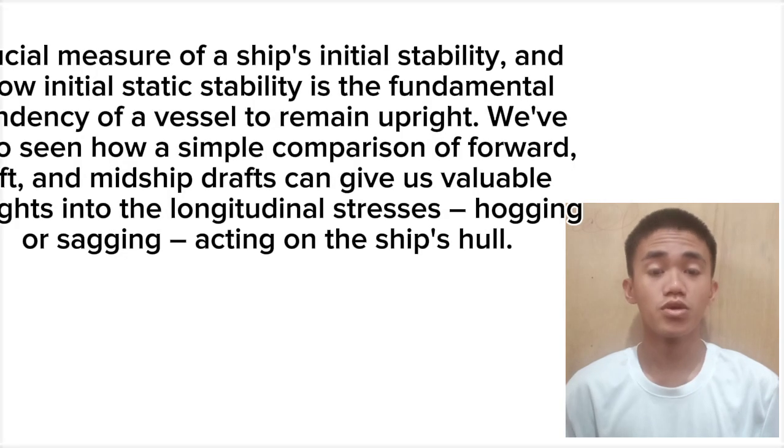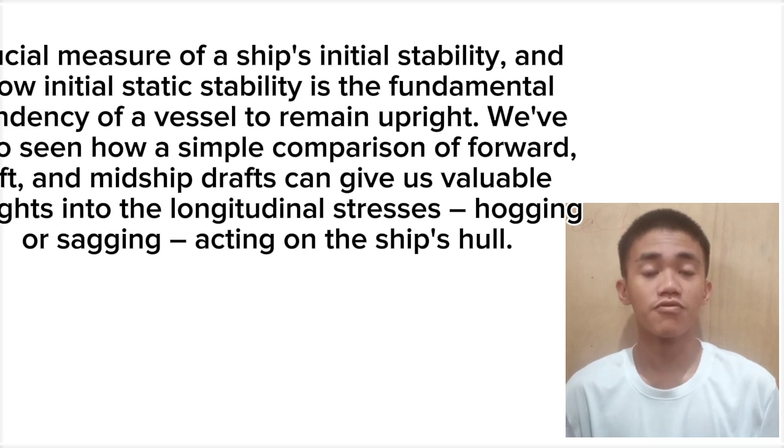In summary, we discussed how metacentric height provides a crucial measure of a ship's initial stability, and how initial static stability is the fundamental tendency of a vessel to remain upright. We also saw how a simple comparison of forward, after, and midship draft can give us valuable insight into the longitudinal stress, hogging and sagging, acting on the ship hull.